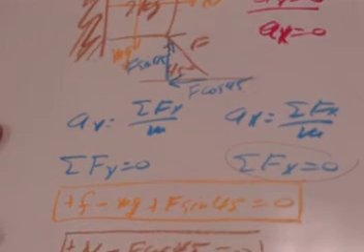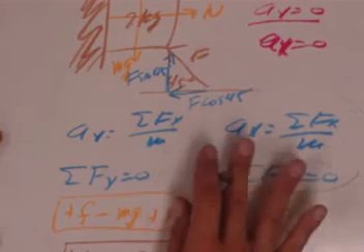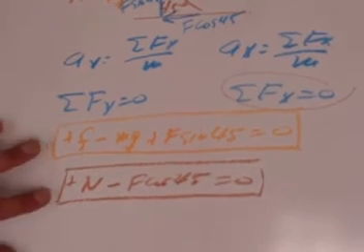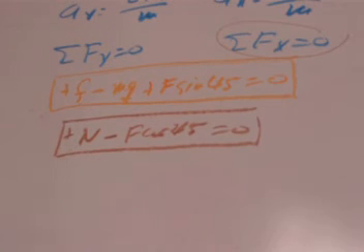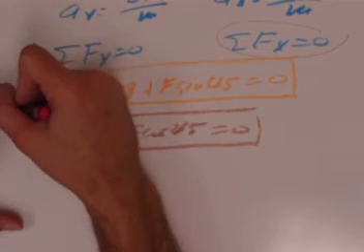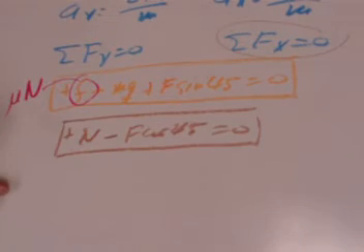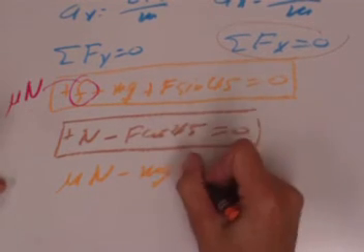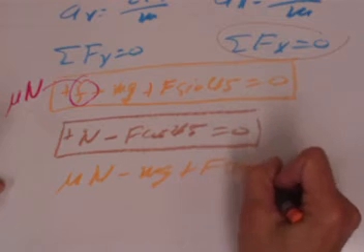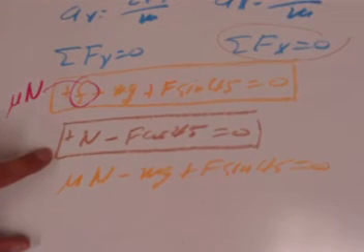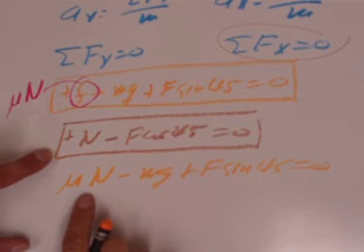So really, we're sort of done analyzing the problem. Look, we've used both Newton's laws in two dimensions, both x and y, and we have these equations for them. We just need to drive home our solutions now to see where the solutions are going to come from. So you look carefully, and this is going to be pretty typical of a lot of these problems, is that the frictional force, remember, is mu times the normal force. We have that in there. So you can rewrite this equation, filling that in: mu times the normal force minus mg plus F times the sine of 45, all that's equal to 0. So that equation gets morphed into this mu times the normal force now.